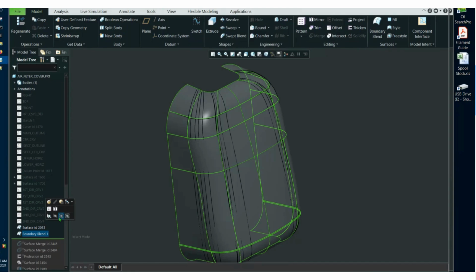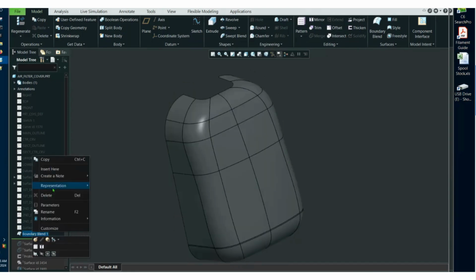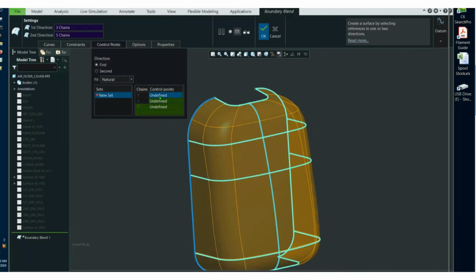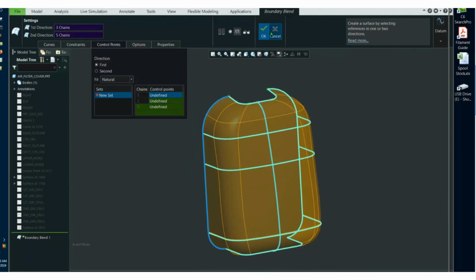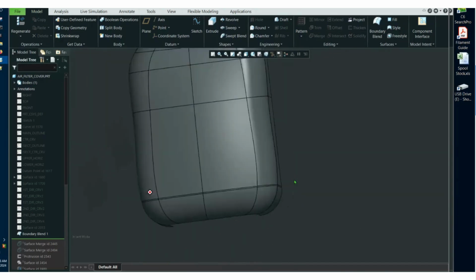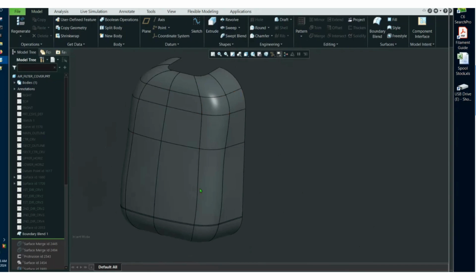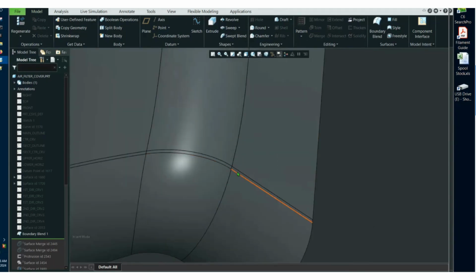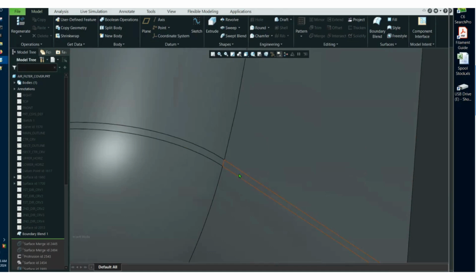Now, in this case, I could have gone in and also done control points on the first direction, but I'm not going to get the same level of feedback quality from the first direction that I got from the second direction, because the only thing I would clear out in the first direction is this double split right here that comes around. Everything else is running on a single seam already. So if we did the first direction, we could clear this little part up right here along the way, and that would be the improvement we would get from the first direction.